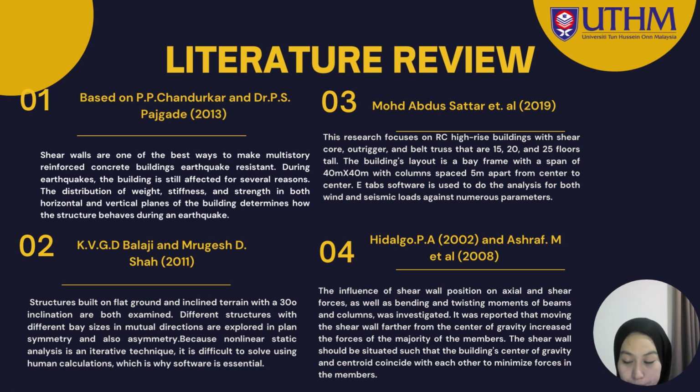The third one is Muhammad Abdul Sattar. The research focuses on RC high-rise buildings with shear wall, outrigger and belt truss that are 15, 20 and 25 floors tall. The building's layout is a bay frame with a span of 40 meters by 40 meters with column spacing 5 meters apart from center to center. ETABS software is used to do analysis for both wind and seismic load against numerous parameters.